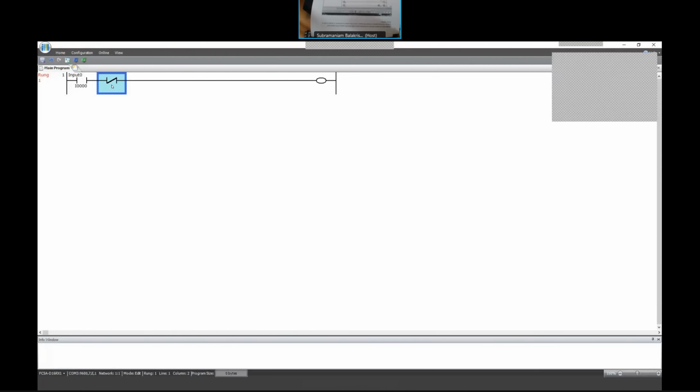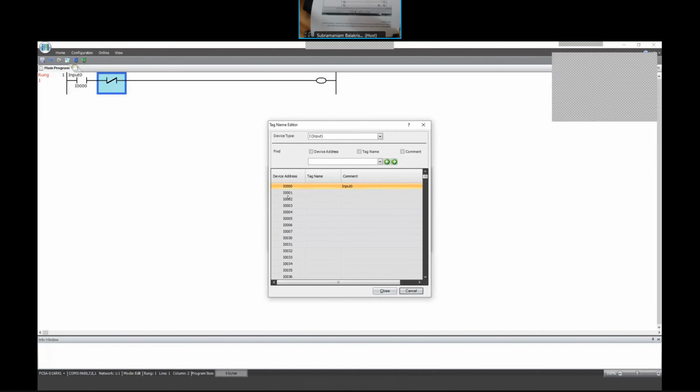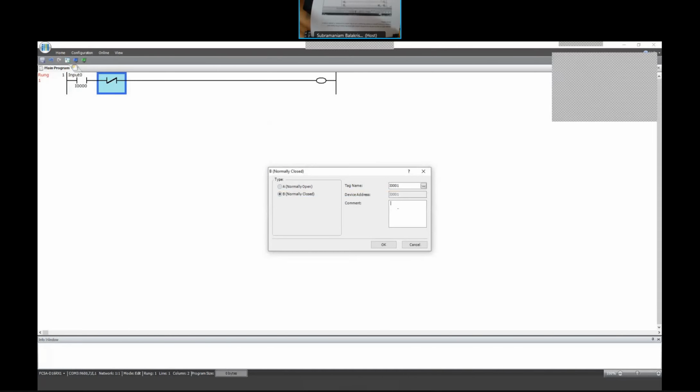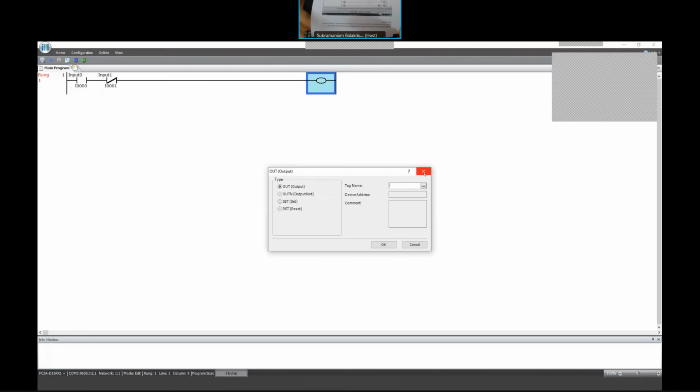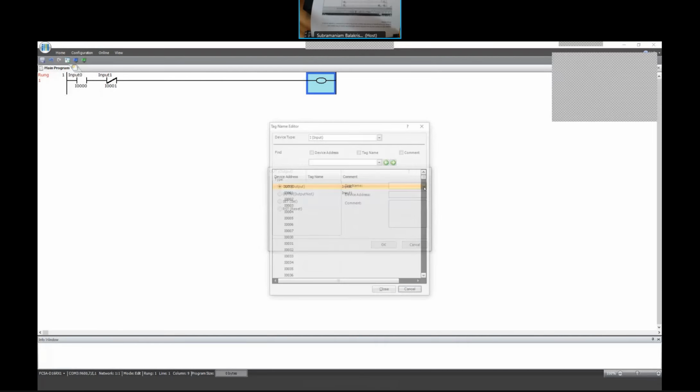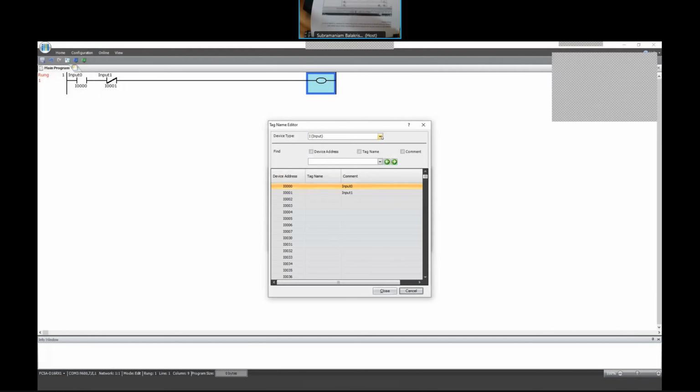Same way, now assign something else to this. I'm going to choose. This time I'm going to see I001. Okay. And I'm going to call it as input 1, but it's a duplicate name. Okay. So this automatically changes to 0 and 1. And nothing in between. I'm going to go to this. Now, watch what's going to happen. The default is input. You should change it to output.